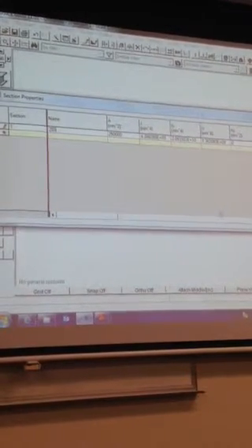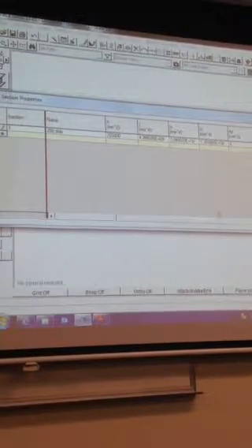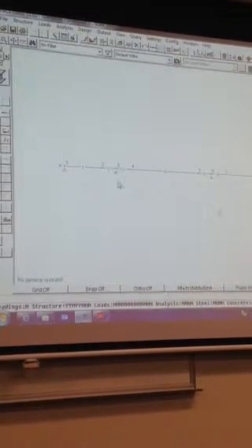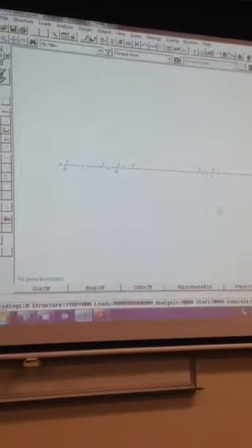So we're going to OK that. But I'm going to rename that so it makes a bit more sense. I'm just going to call it 250 thick slab. We're going to OK that. Down the bottom, you can see the grey section number 1 is 250.